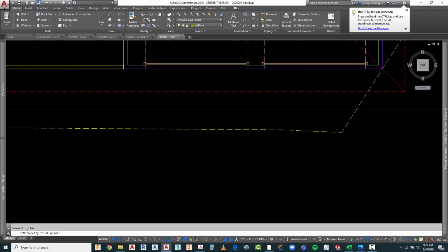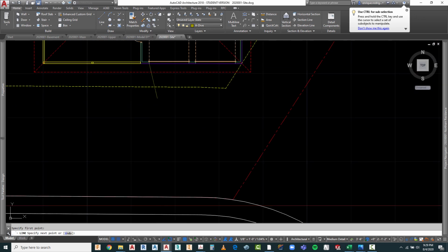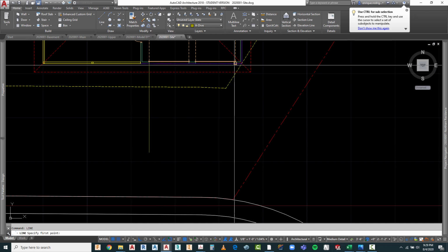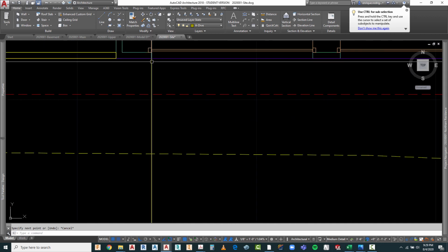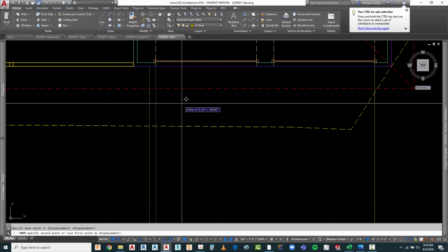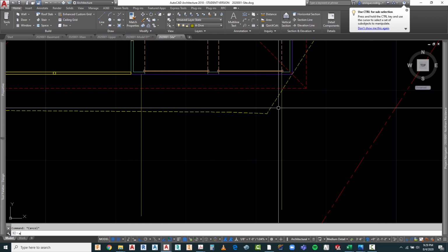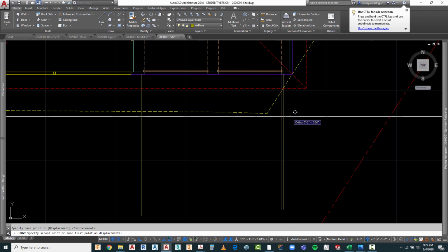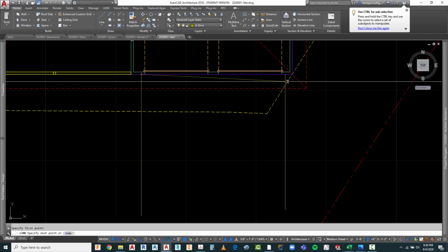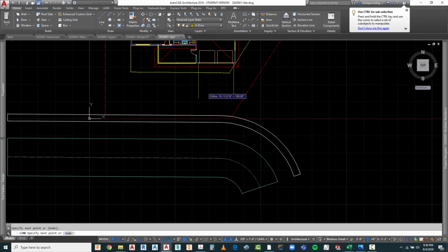The way that I usually start this is I'm going to draw a line from this point, put my ortho on, and do one over in here. Now, usually I don't like to start the driveways directly where the garage door is. So I'm going to move this. I can also use offset or copy. I'm going to move it about 6 inches over, and do the same thing for this one. Now this is no different than our sidewalk or our road. We have to make sure that we create a closed polyline, so we need to close off at that point.